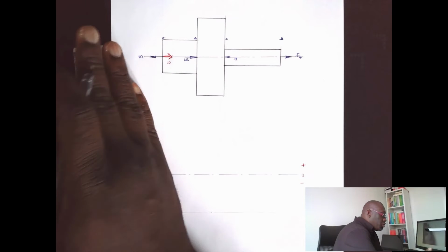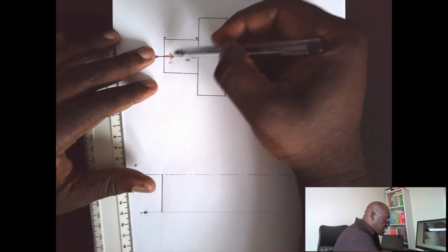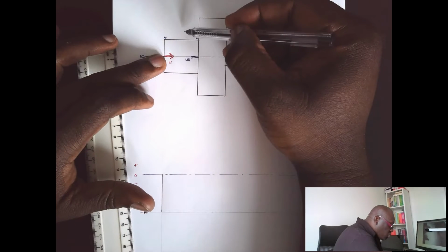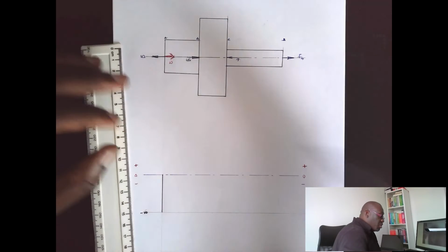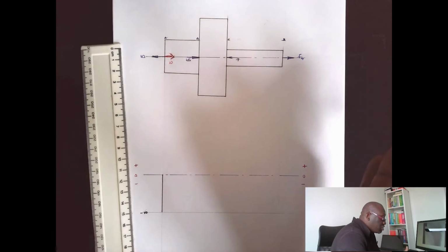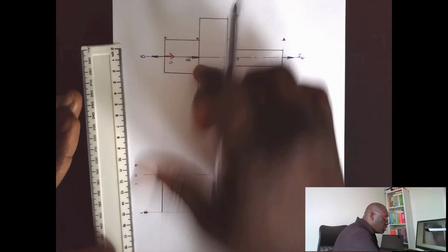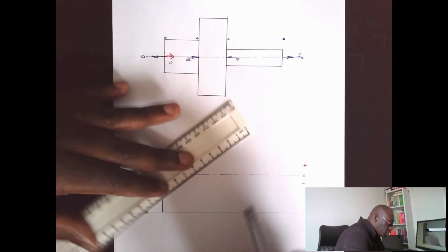We're also going to assume that since there aren't any forces countering the 10 kilonewton force across this sectional profile of AB, the compressive force is constant along that until we get to interface B, where we've got the 15 kilonewton force.